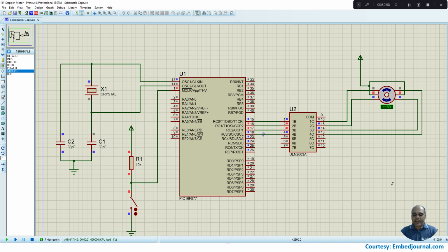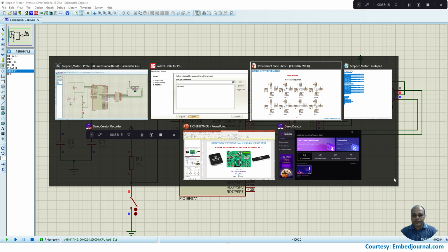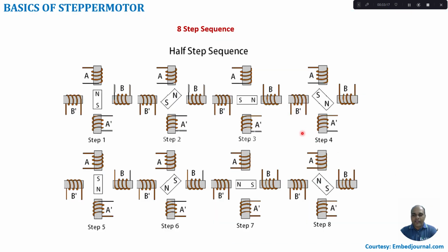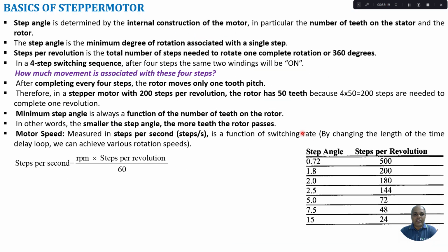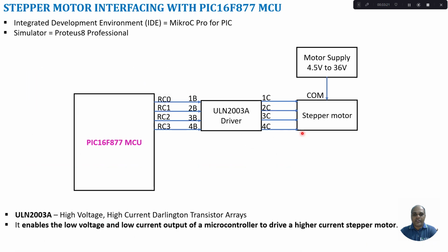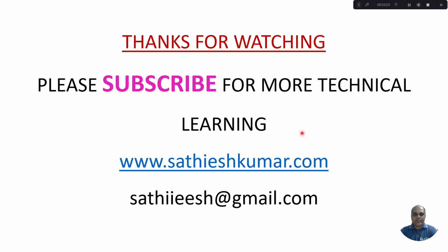Thereby we can easily connect a stepper motor with a microcontroller and we can do the programming in both clockwise and anti-clockwise direction. Here we have used the biphase 4-step sequence for a stepper motor. In this tutorial, I have discussed how to interface a stepper motor with the PIC16F877 microcontroller.